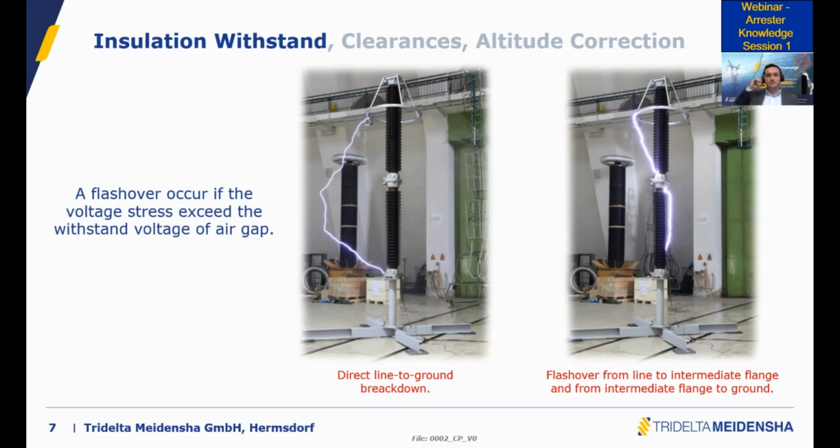Yes, you're right. On one hand, you have to make sure that your surge arrester is suitable for the pollution zone you are installing it at, and you have to make sure that the surface current is not so high that the surge arrestor will flash over on the surface due to a rising current and conductive layer.